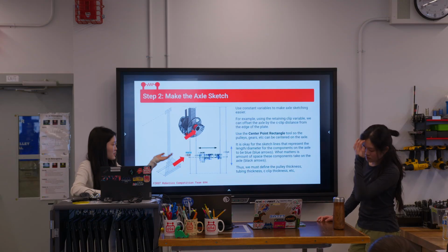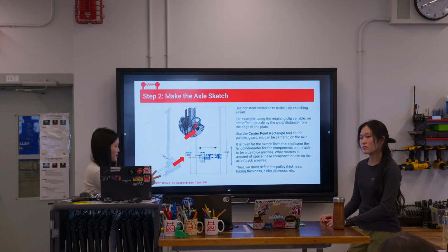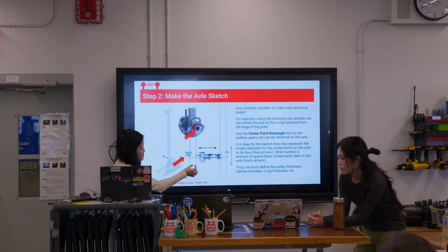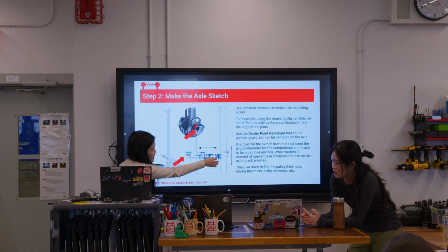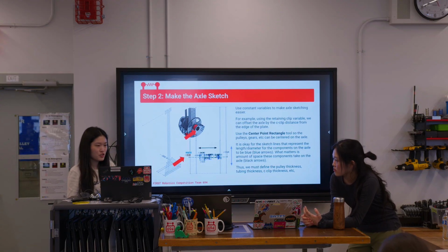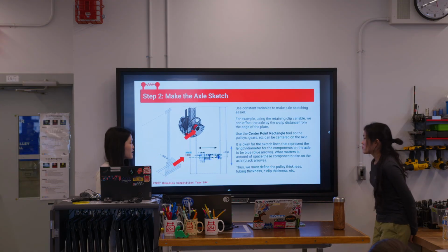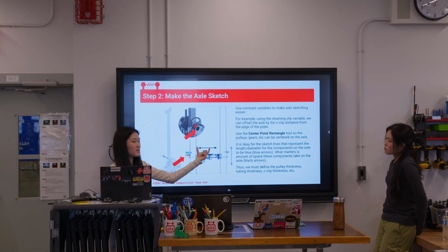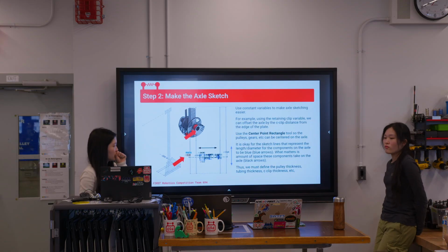So you click on that plane, and you start dimensioning out. I already had these bases, so then I can start adding my pulleys. I know the minimum distance I want to be, and I know where I want the bearing to be as close as possible to a structural part. So then I start defining all that. I remember the blue part I didn't define, but you guys can define if you want. What matters is the black arrow, the distance between them, that's taking up space.